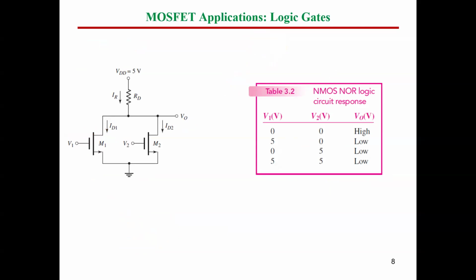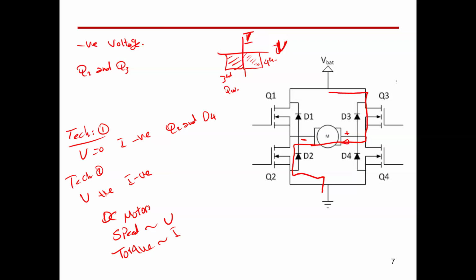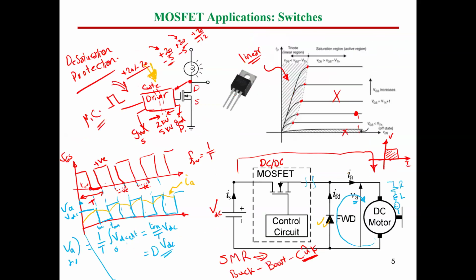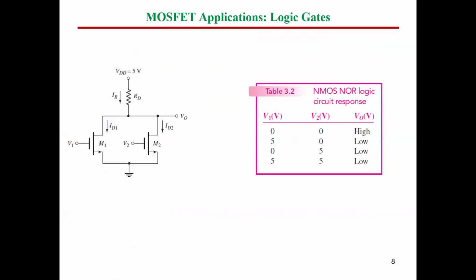All of these circuits we use now, this circuit or that circuit, use the MOSFET as a switch, and the MOSFET as a switch will be in the linear mode. How can we control it in the linear mode again? We have to be sure that V drain to source is less than V drain to source saturation and apply the gating pulses with the voltage we need in order to allow the higher current to flow in our circuit. So this is the first thing here.